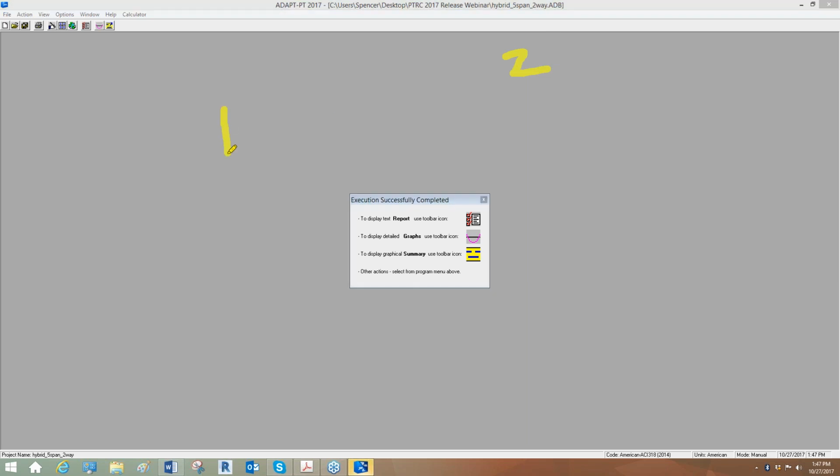So if we look at an interior column, for example, we're basically assuming that each side of the column, because it's an interior condition, means a 4-sided critical section. Therefore, we would have 2 rails assumed per side. The user can modify this. I could say there's 2 on one side and 3 on the other side. So in this case, we have two on every side.